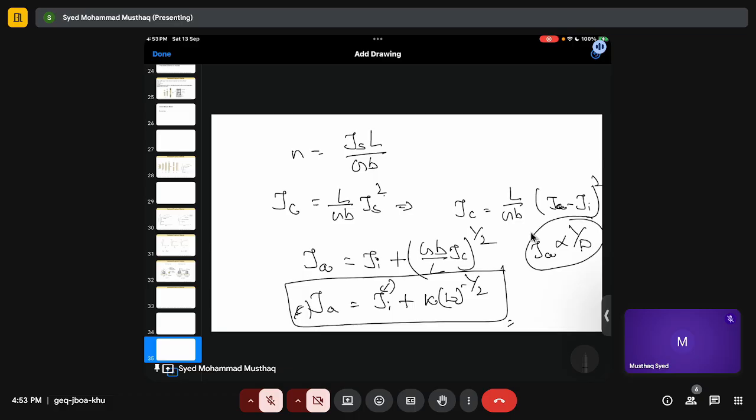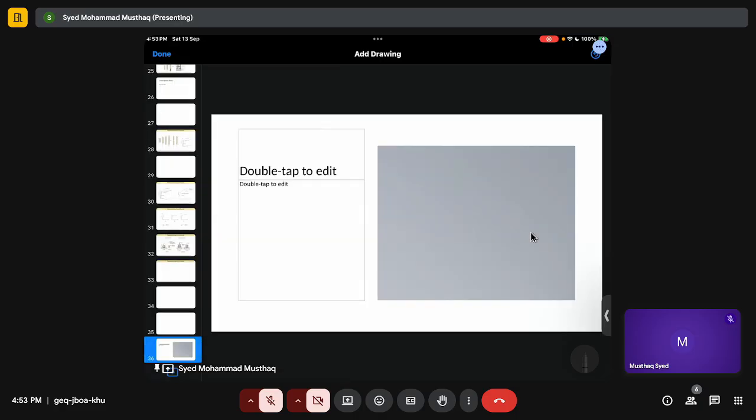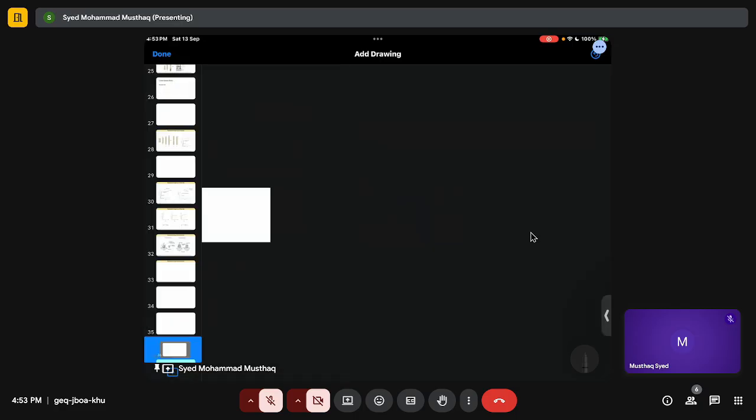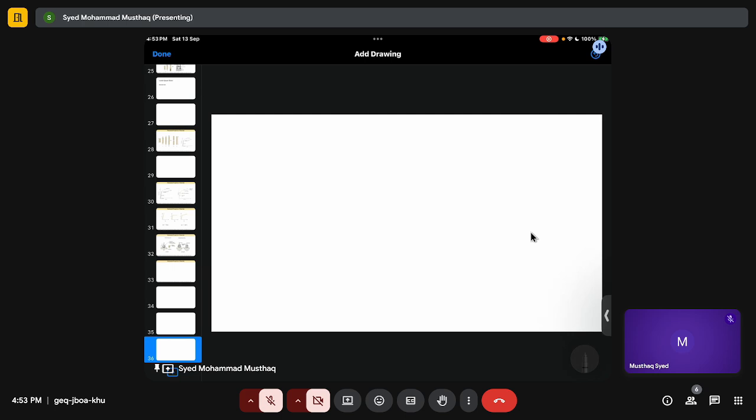So this is for bulk materials. And if you go to nanoparticles, because nanoparticles have high surface area and are very small, they cannot accommodate dislocations, first of all. The next thing is, because the surface energy is so large, there will be sliding also.